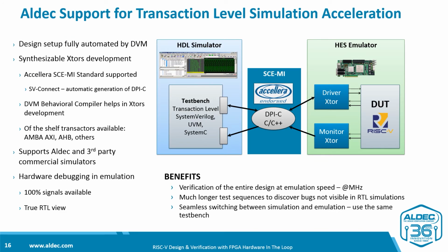So, hardware in the loop improves the verification process, and this is how we help to integrate it with your DV environment. Building FPGA prototypes might be quite difficult and painful, but it shouldn't be so in emulation, where changes in the design are still quite frequent, and emulation needs to be rebuilt without too much effort.